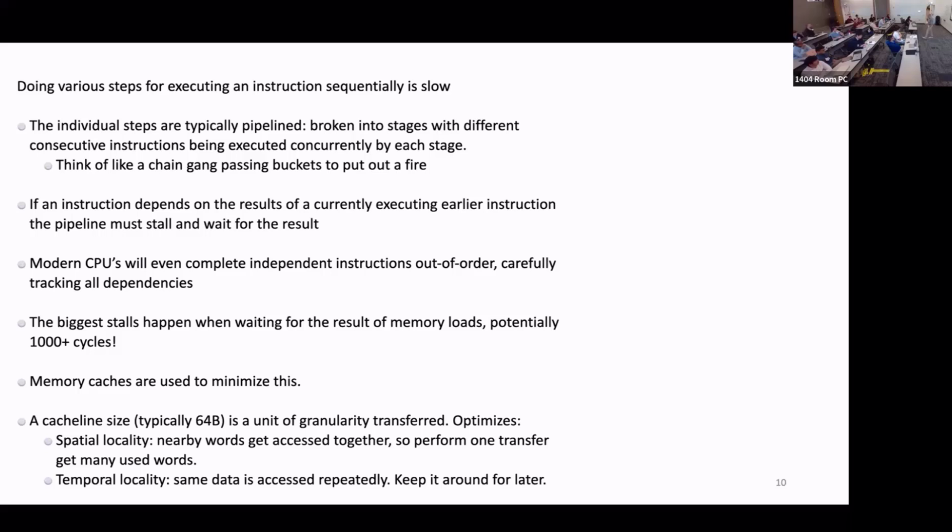And the idea is that you have the instruction fetch portion fetching an instruction and then handing that over to the decode and going and fetching the next instruction before the whole process is finished. That, of course, means that if the program flow decides to do something else and it's fetched the wrong instruction, you have to cancel out and remove stuff, right? And potentially, if you have an instruction that's clearly dependent on an earlier instruction, right, you have to wait until the earlier instruction has completed before you can execute the dependent instruction. That's called a pipeline stall.